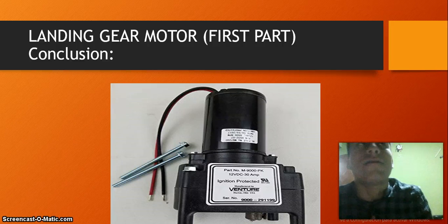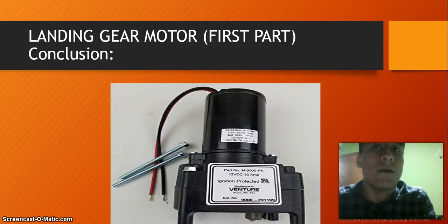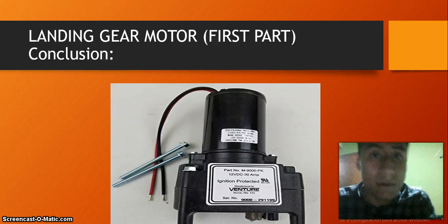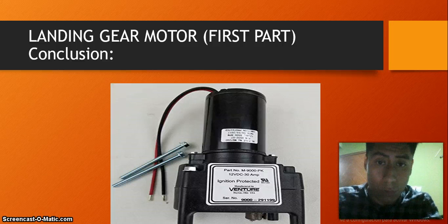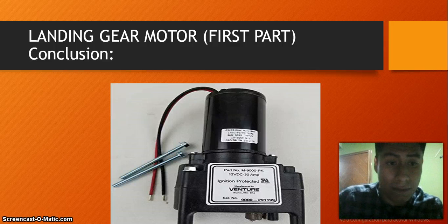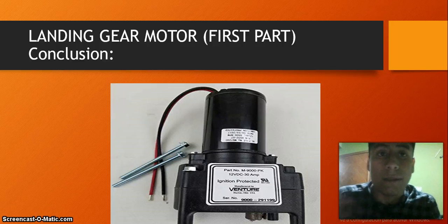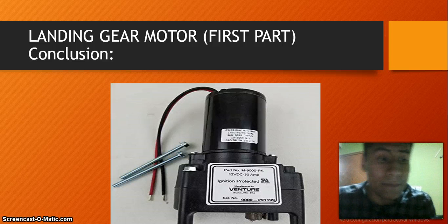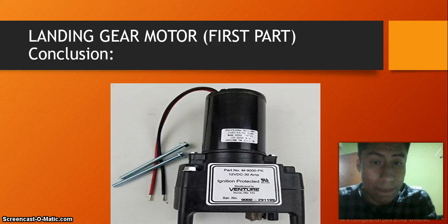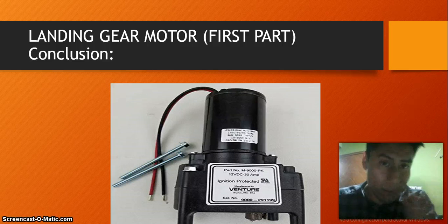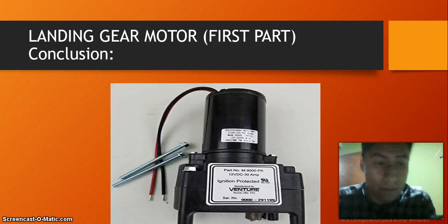Well, we have measurements of resistance of the cables. The ground wire of the brake coil and the motor is in one cable, a ground according to the diagram, and the measurement of this cable is 1.25 ohms. The green motor cable and the brake hold cable are united in one cable, and it is also 1.25 ohms.